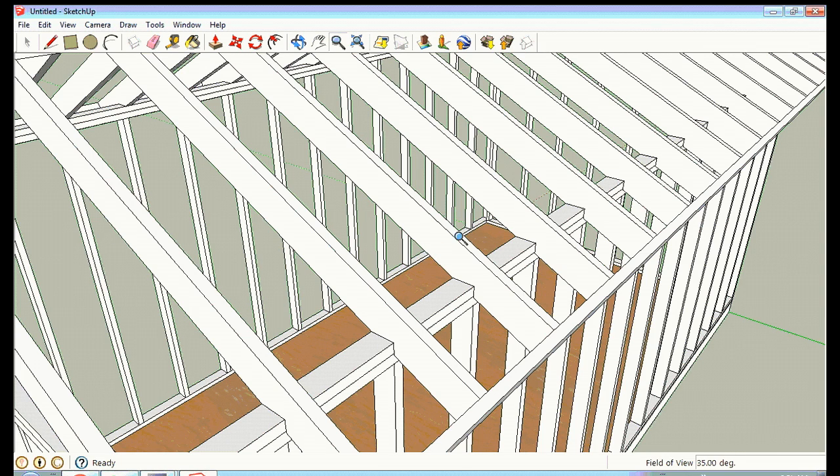And you would put that on the roof joists. You don't have to put it on every one, but you need it on about every other one of your roof joists, so that it prevents the wind from catching underneath this and lifting the whole roof off. So a hurricane tie is also recommended even if you're using bird's mouth. But the bird's mouth is a very strong construction method and used on almost all houses.